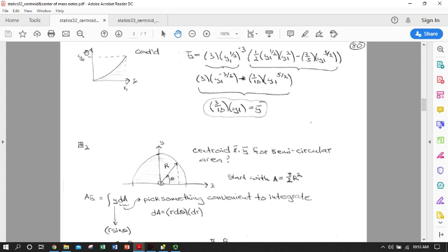So if our upper limit that defined our centroid area of interest is y1, y bar is going to be about a third of the way up, just shy of a third. So x bar was at 3/4 of the way from 0 to x1, and y bar is just shy of 1/3 of the way from 0 to y1.